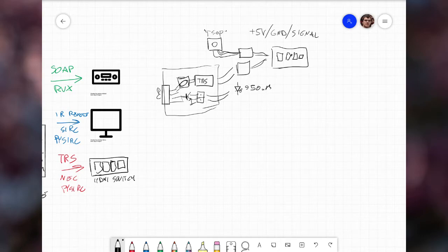because yes, the grounds should all be the same, because this HDMI switch is actually powered by a USB power adapter that doesn't have a ground. All the grounds should be safe to put together. I wasn't entirely sure. The opto isolator is 20 cents. 20 cents, even 10 of them, is much less than buying a new HDMI switch if I burn it. So I just opted for the opto isolator and I'm done.